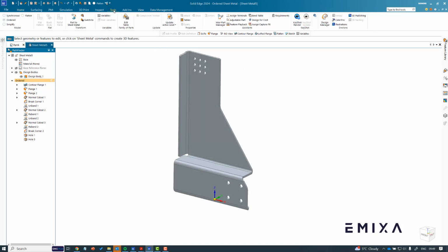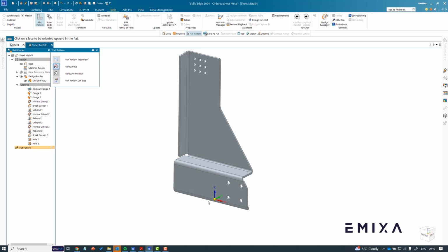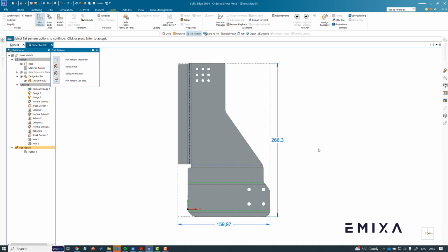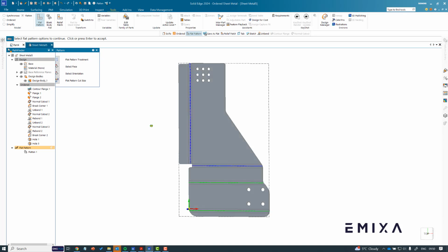Let's just do a quick flat pattern. So let's go tools, flatten, choose this face, and then this edge on here. This is parallel to the x-axis with a dot at the correct orientation. That means that our flat pattern and our model orient correctly. And we can see in 2024 we've got lines showing bending down, bending upwards, etc. Color coded on there. Okay, that one's now complete.